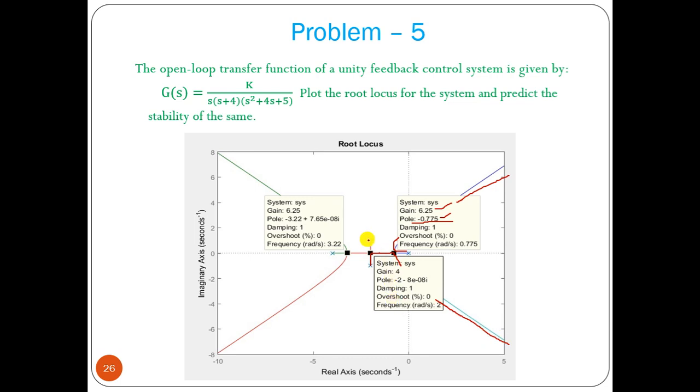This complex pole departs at minus 90 degree angle, comes here, breaks away, and goes this way along this asymptote line to infinity. This pole comes here, okay, breaks away, and it should go along this asymptote line to infinity at a particular angle. That angle of asymptote we already got. So we can see all the gain values and the breakaway points, and we can see all the gain values that we have calculated are the same.